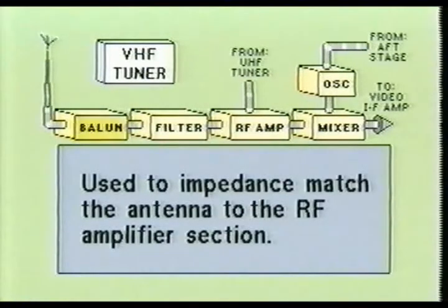The Balun transformer is used as an impedance matching device between the antenna and the input of the RF amplifier stage. The Balun transformer plays a key role in reducing the electrical noise caused by the antenna line.